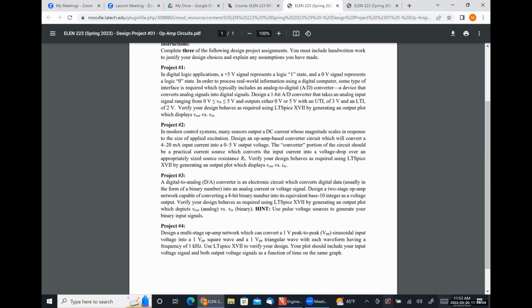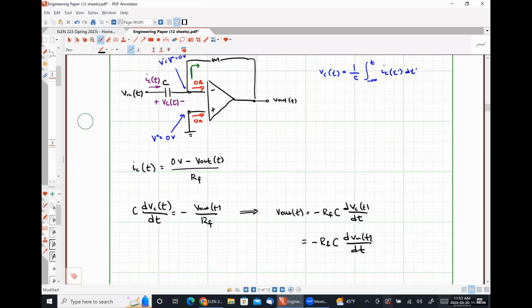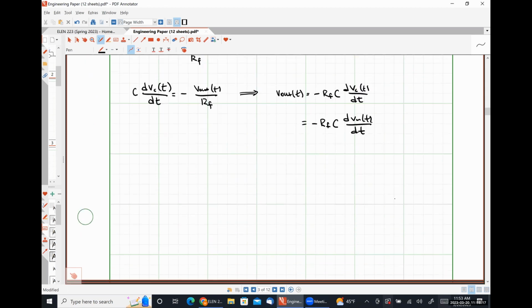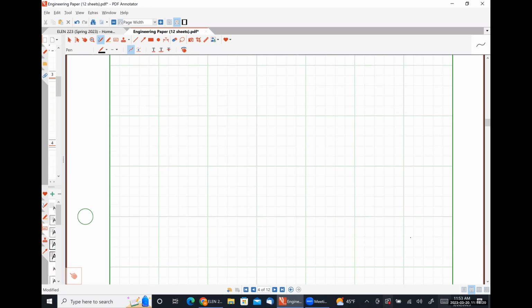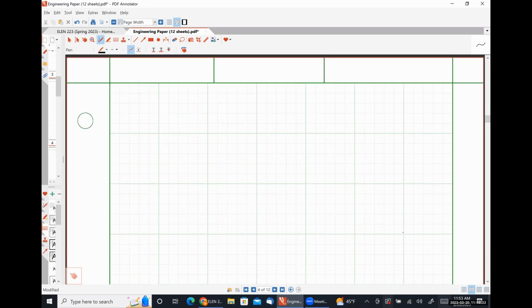All right, so my screen will switch back. Now we're going to make an integrating circuit by the magic of swapping the R and the C. So literally the exact same circuit, except we are changing the position of our resistor and capacitor.